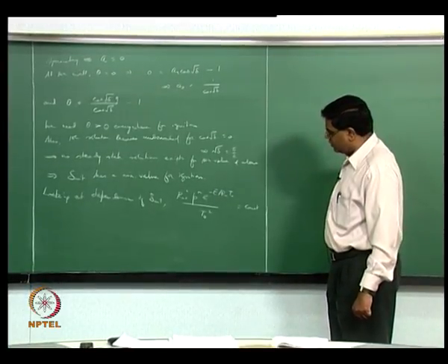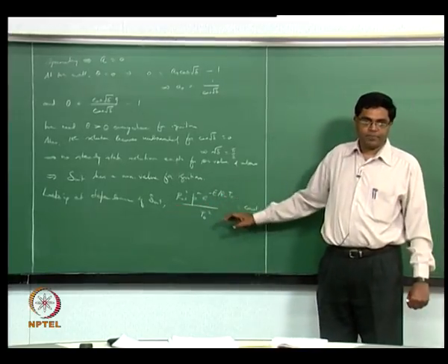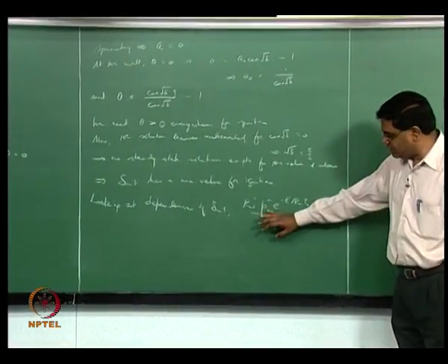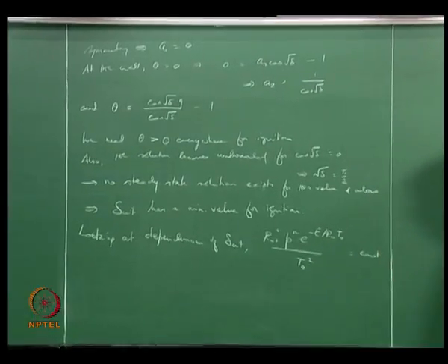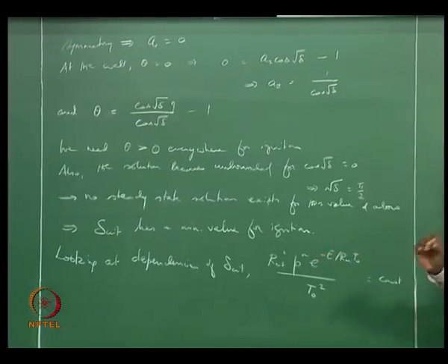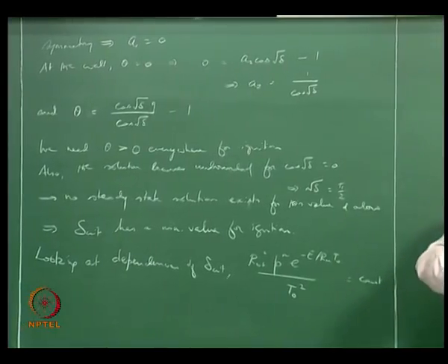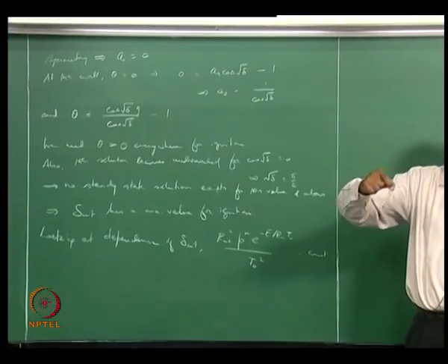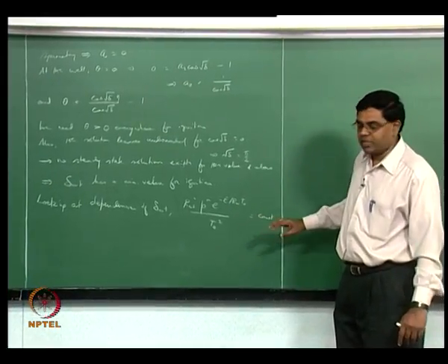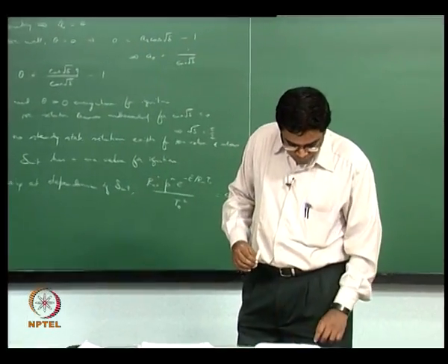So we assumed a steady state process and then looked at when it is violated. So this formulation is somewhat limited in the way it is done, but the most important thing that we are looking for is the dependencies on pressure and temperature, the pressure of the system and the initial temperature of the reactants. Therefore we simply say this should be equal to a constant, or if you now have this greater than a constant, then you will have ignition. Or if you want to avoid ignition, like for example you have a very narrow tube and reactant mixture being sent through the tube and you want to make sure that it doesn't get ignited, then the R critical should be less than this constant value, right. So the actual value of this is typically obtained empirically.